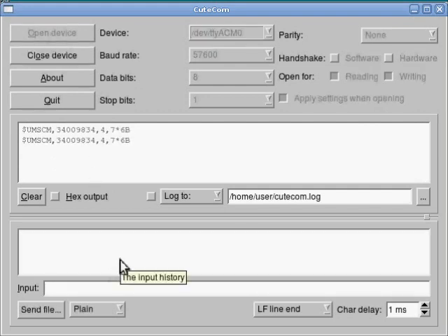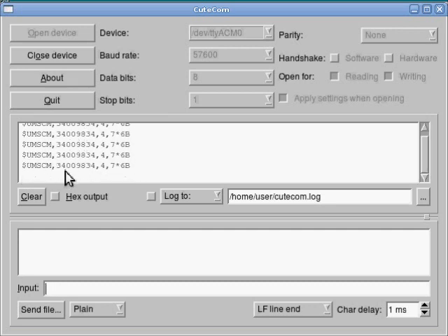Okay, here we are connected to the Grid Insight AMR USB-1 utility meter receiver, and you can see that in QtCom we are receiving data from the serial device here. This is standard NMEA 0183 sentence format. You can look that up and find all sorts of documentation on the format. Basically, each line is a separate data sentence coming in from the receiver over the serial line.